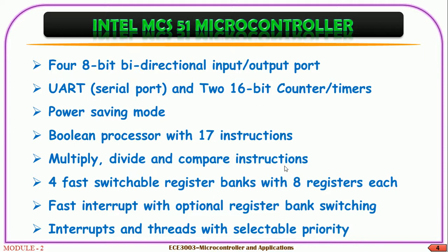It has four 8-bit bidirectional input and output ports, it supports a serial port, it has two 16-bit timers and counters, and it operates in power saving mode.